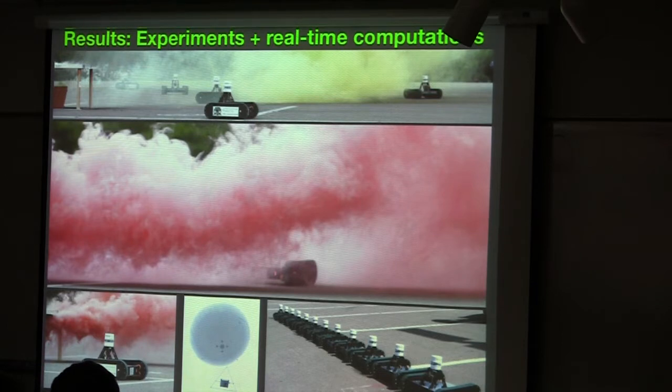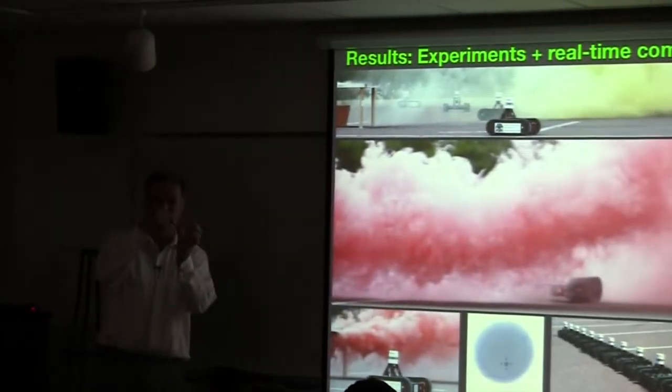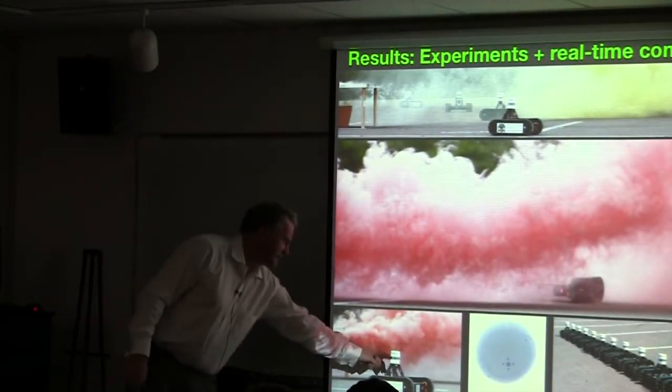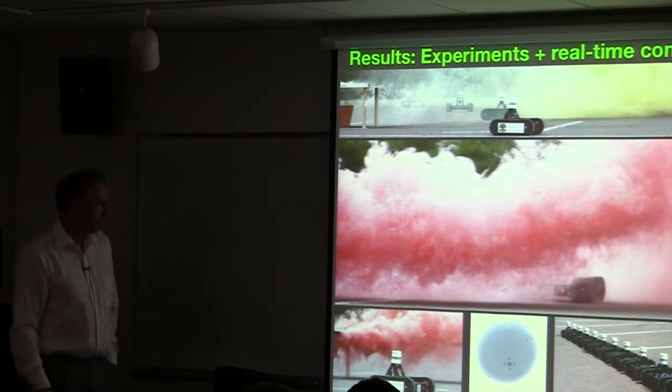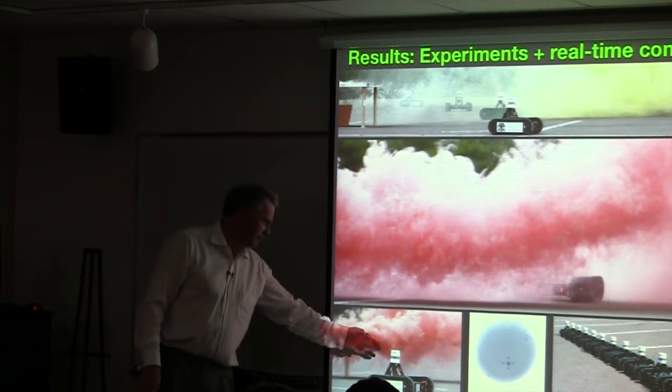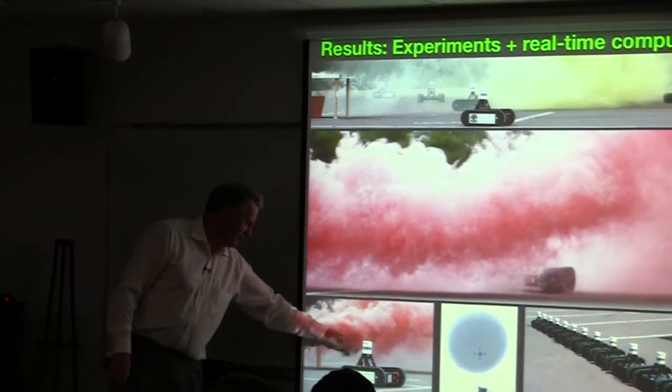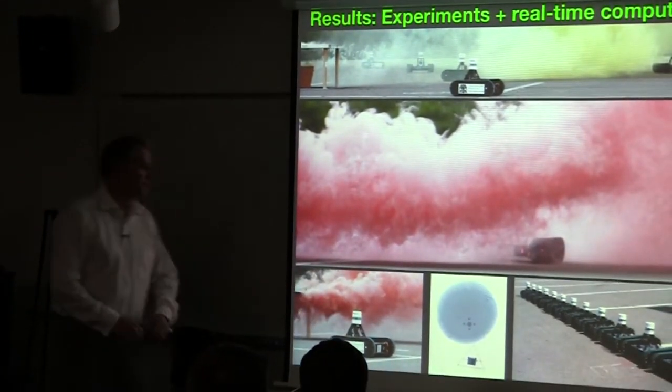On the top of each of these vehicles, we have an off-the-shelf sensor that's actually designed for sailboats that can measure the X and Y components of winds. It's got a sonic anemometer: it makes a sound, listens to it, between the three posts, and by measuring the time that it takes sound to propagate, it can get wind measurements. Very nice off-the-shelf component. It also has a GPS, albeit not a very good one, built in, and a magnetometer. And we also have a particulate sensor on there.